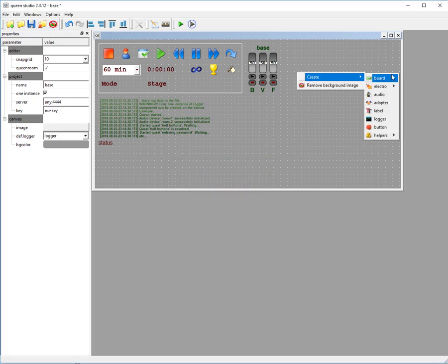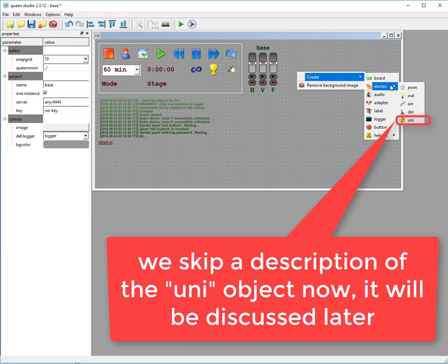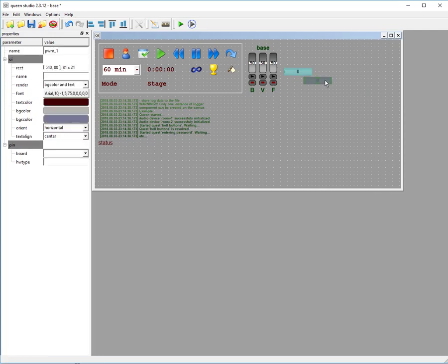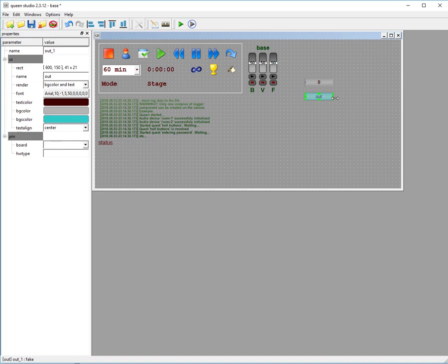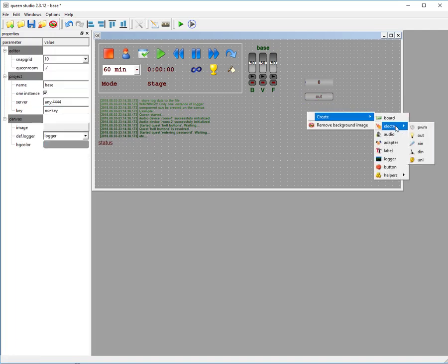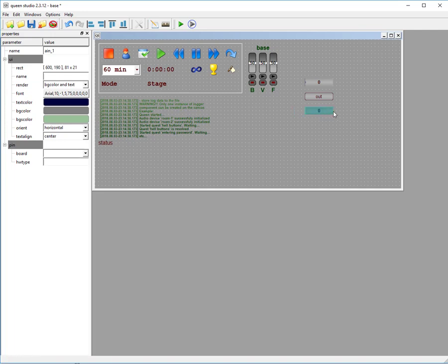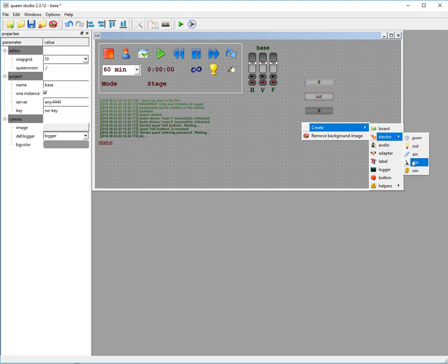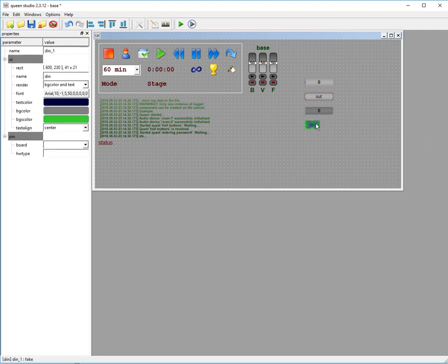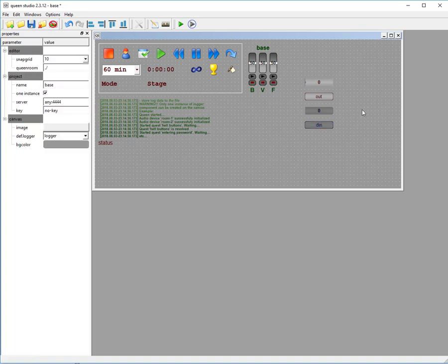To access escape room electronics that plug into the PLC boards we create, components are combined in the Electro submenu. Queen supports 5 types of electronic types. PWM is used for smooth control, like LED lighting brightness. Out is binary or digital control for switching on or off any kind of electrical devices. AIN is an analog input to handle different sensors with a range of input parameters, like photoresistors, pressure sensors and so on. DIN is a digital input to handle sensors with a binary signal, like buttons, reeds and limit switches.